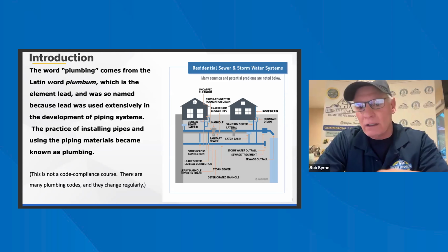Inspect wastewater treatment, water storage. Evaluate time to obtain hot water at fixtures. Evaluate and determine the adequacy of combustion air. Right, you're not going to determine adequacy, but if you're looking in a boiler room and there's no combustion air coming in, you might want to comment on that.